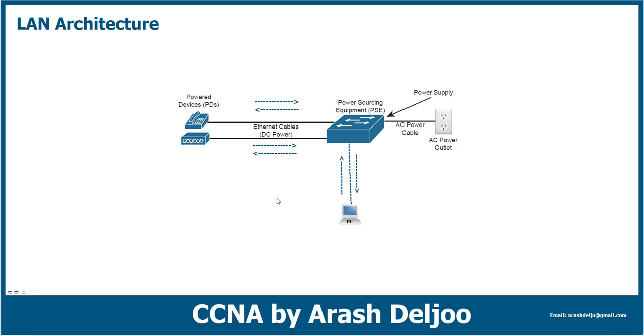Or maybe in some cases we have other solutions. For example, in some powered devices, when the device is off, the pin in and pin out are connected to each other. This means that the device is in a short circuit status. Because of that, if you send a little signal to the other side, you will receive the signal back, and this means that this is a powered device. Also, we have other options for detecting whether the next device is a powered device or not. This is not important for us.